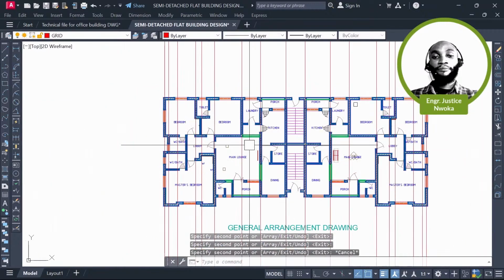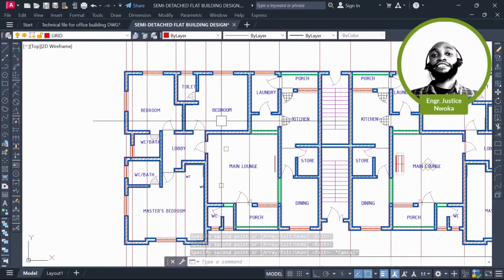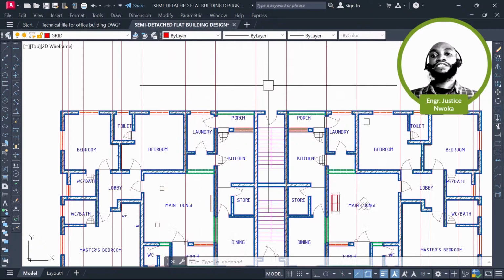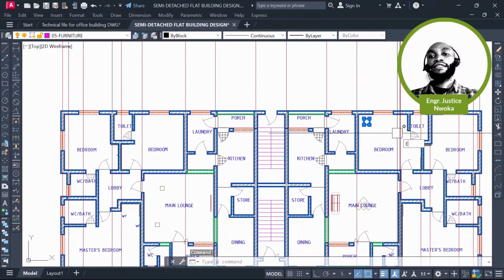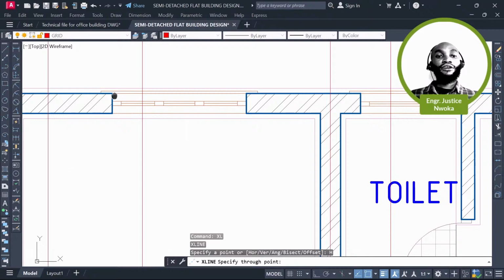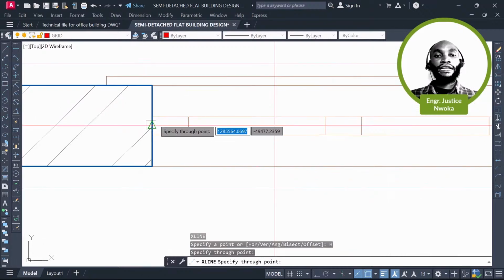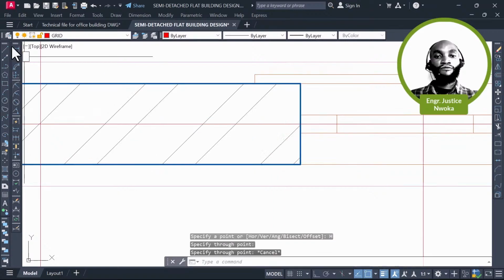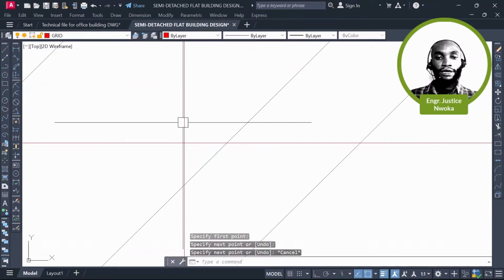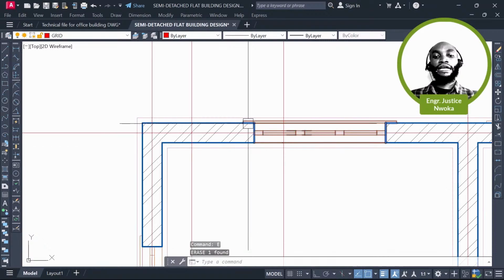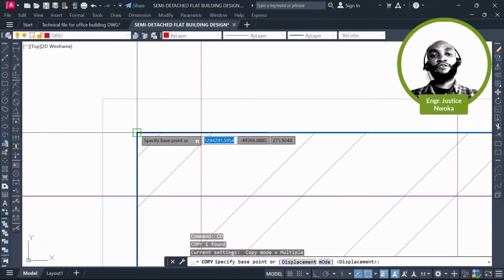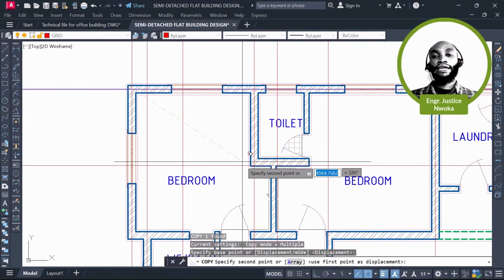So right now we are done with our vertical grid lines. Okay, if there is any other one, we will just look at that later. So right now we are moving into creating the horizontal grid lines. Okay, so right now I'll just type XL, enter, H, enter. All right, so you just press on that H and then begin to place at the center. Let me just confirm if this is the center by using the line right now. And then come here, click here, and then click here, and make sure that's the center. Yes, that's the center. Okay, that's fine. So I'll just erase that, and then copy again, repeat what we did before by copying this right now, and then come here and begin to place on all the horizontal walls.